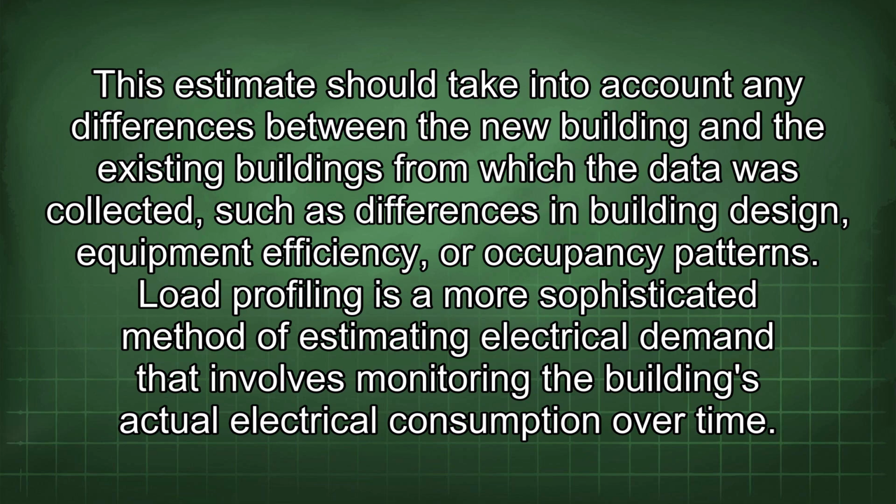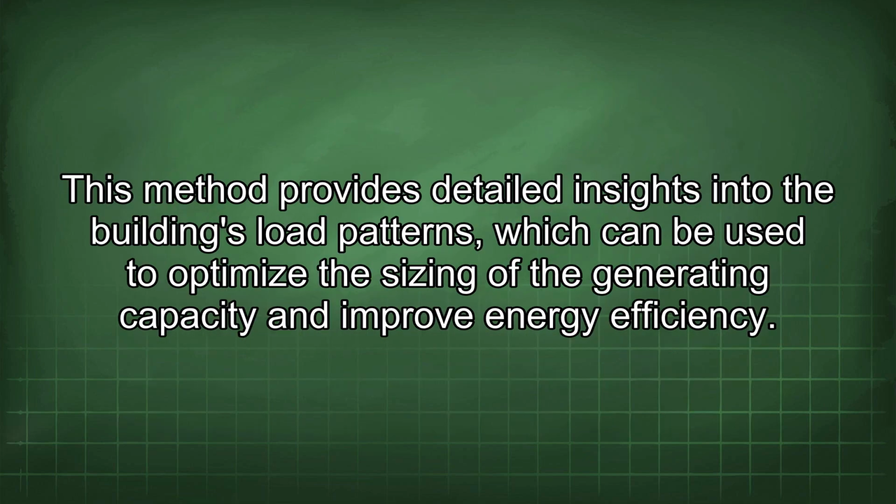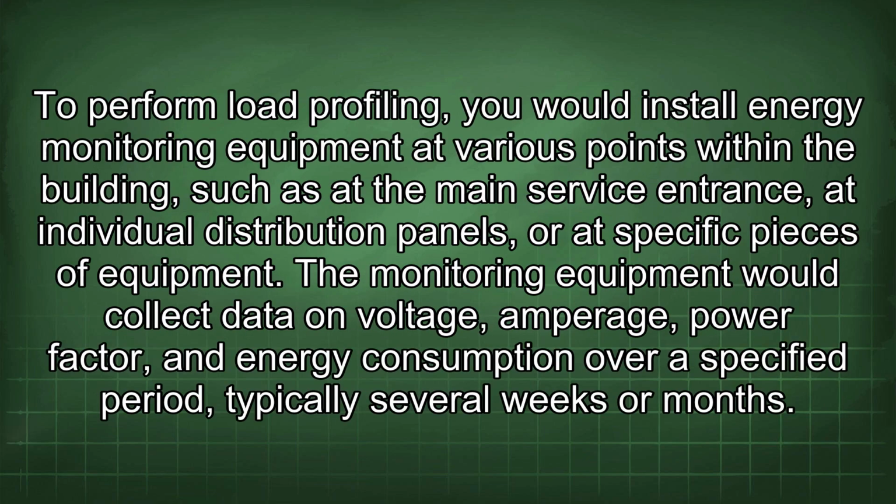Load profiling is a more sophisticated method of estimating electrical demand that involves monitoring the building's actual electrical consumption over time. This method provides detailed insights into the building's load patterns, which can be used to optimize the sizing of the generating capacity and improve energy efficiency. To perform load profiling, you would install energy monitoring equipment at various points within the building, such as at the main service entrance, at individual distribution panels, or at specific pieces of equipment.